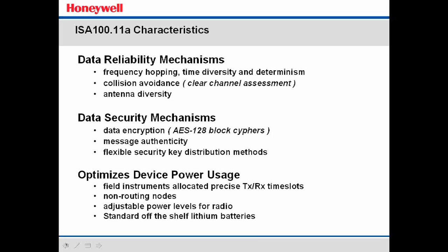So the reliability portion of that is this: the wireless device manager knows it was expecting that particular transmitter at that particular time. If it doesn't get it, it goes out and asks for it. So that's the reliability portion of that. Collision avoidance.